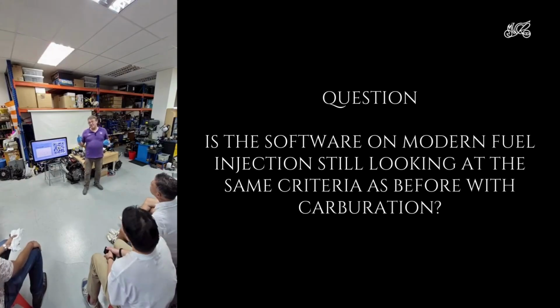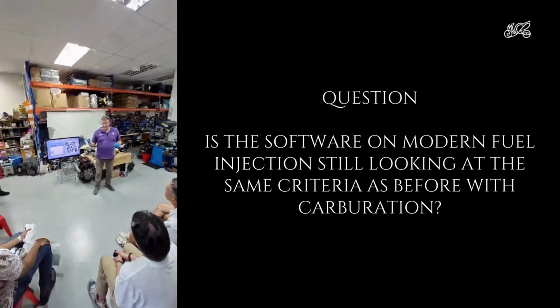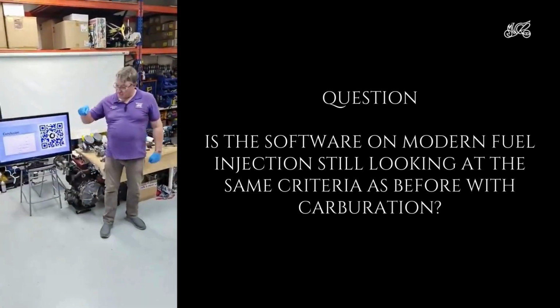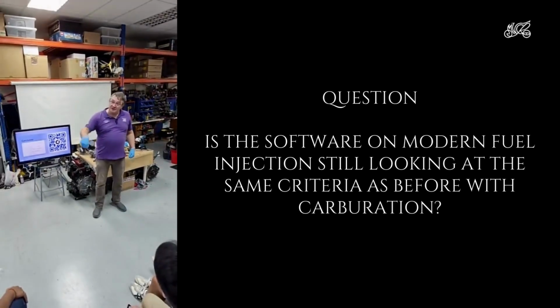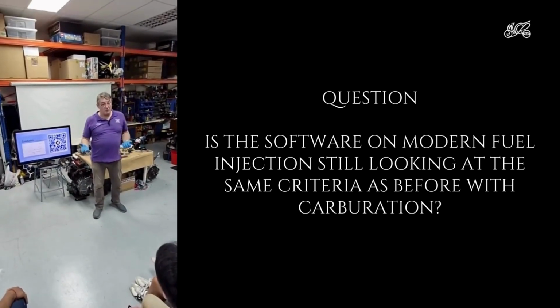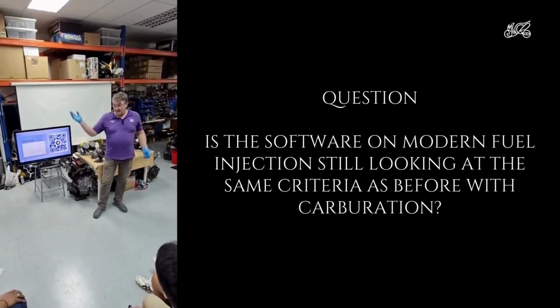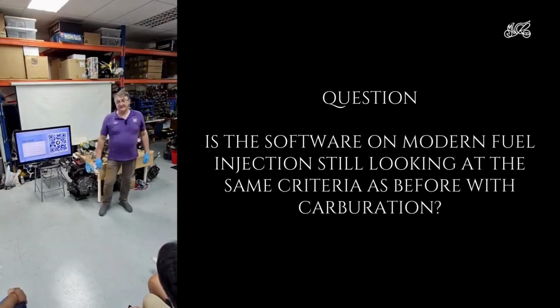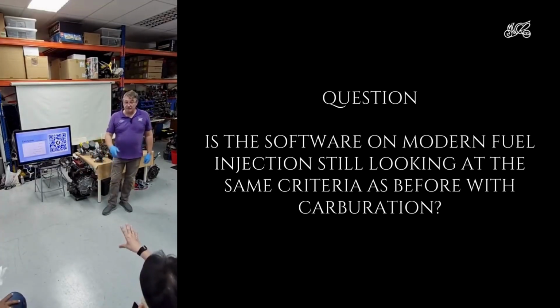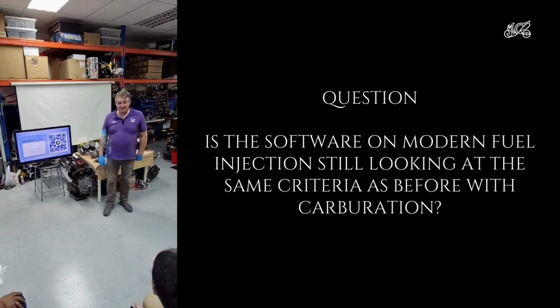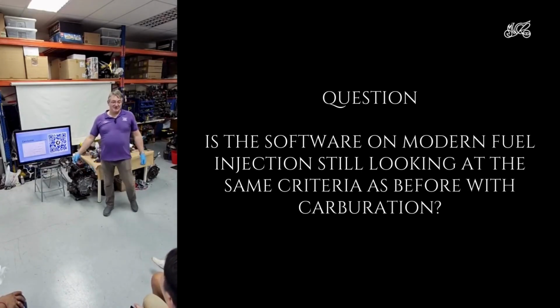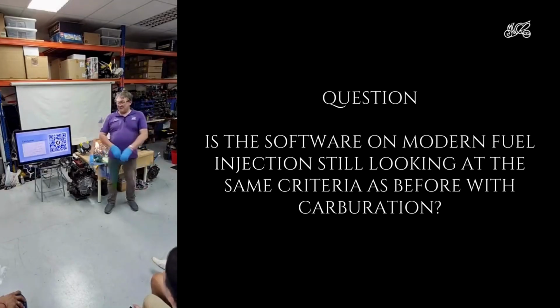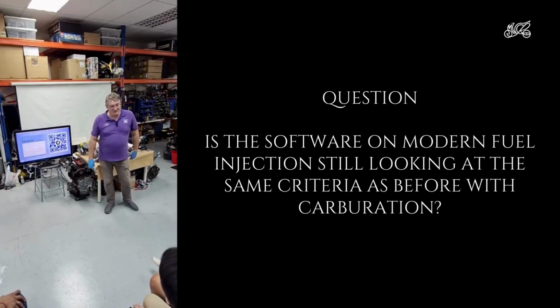And the US government realized this was a huge problem, and so they mandated onboard diagnostics. So there was a standard plug, and you could plug into the computer and it would tell you what was wrong. And that's now standard on all vehicles. So all vehicles are reporting which sensor's gone bad or what they don't like. So because of the US? It was driven by US mandate, yeah, because of the problems they got into, where you just have to replace everything at random until the problem goes away.